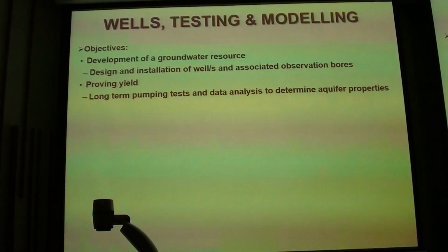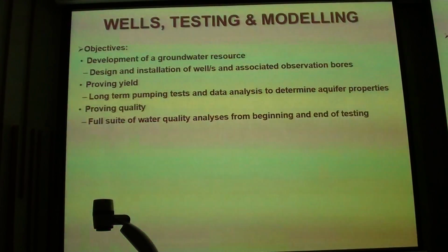Prove the yield: long-term pumping tests, so taking lots of water out of the ground at the rate we want it to go for a long period of time, making sure that the aquifer behaves itself, and also we will get data from that. We will be able to determine the aquifer properties, transmissivity, storativity, and hydraulic conductivity, which are values we need when we come to modelling the thing.